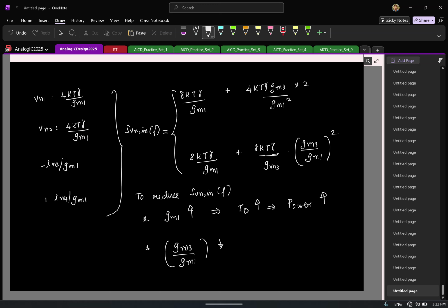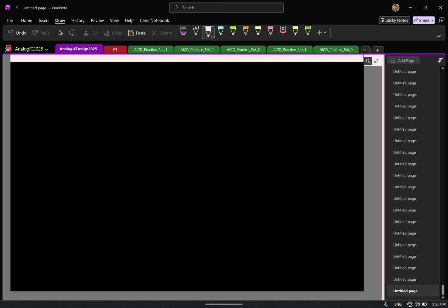Cool. So now we have looked at the noise. It turns out even offset can be easily analyzed in the same framework. That will just take a couple of minutes, so as we'll see. So remember, we already know that transistors will have mismatch, and threshold voltage mismatch is the dominant factor. And the way to model threshold voltage mismatches, you assume that the mismatch in the threshold voltage is added as a small signal voltage at one of the gates.